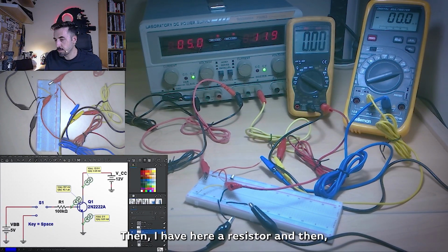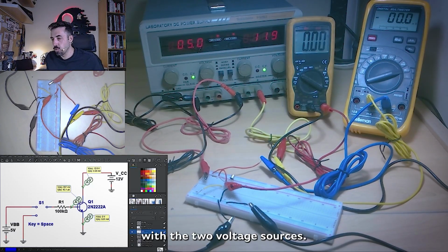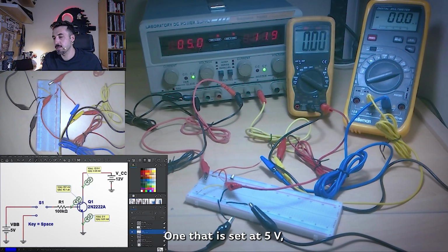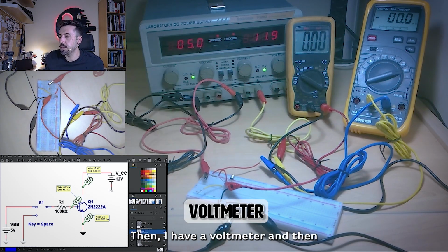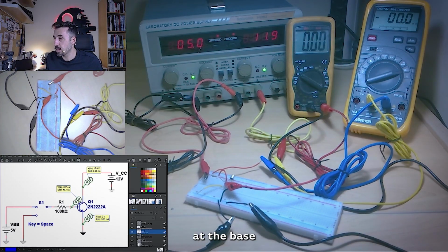Then I have here a resistor and then my power supply with two voltage sources, one that is set at 5 volt, the other one at 12 volt. Then I have a voltmeter and then an ammeter. The voltmeter is measuring the voltage at the base, and the ammeter is measuring the current through the collector.